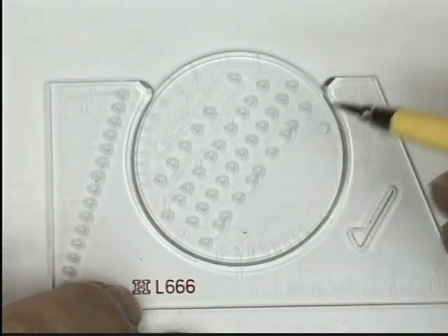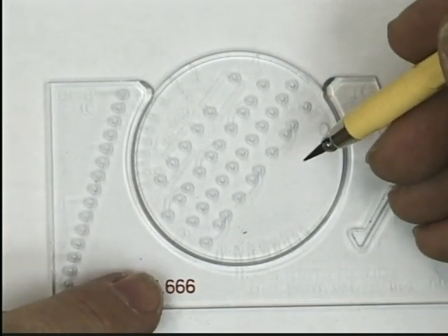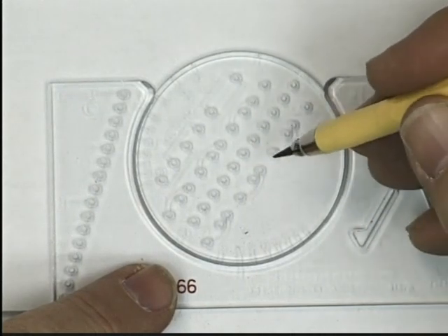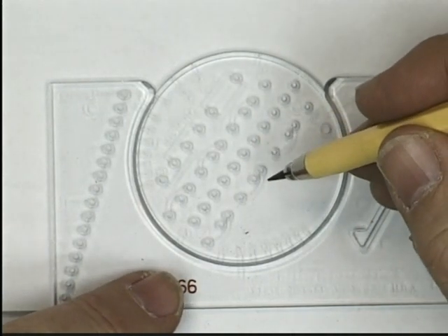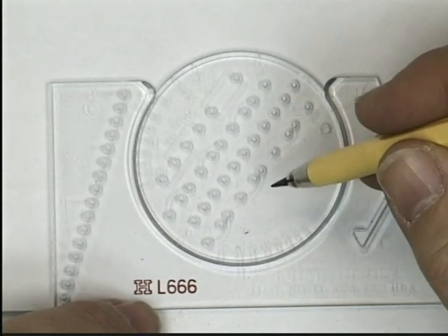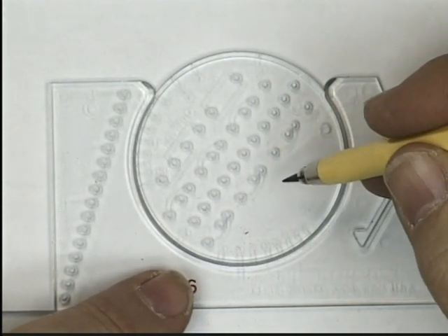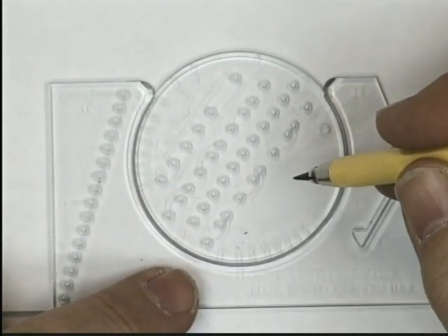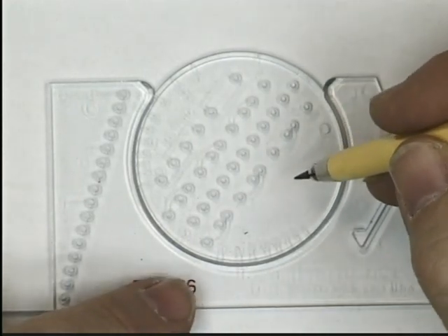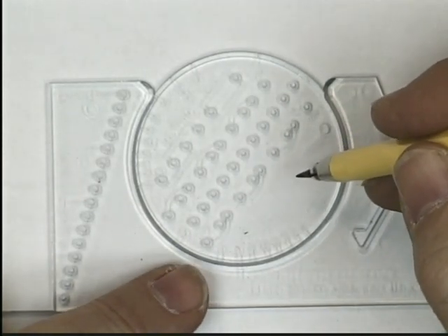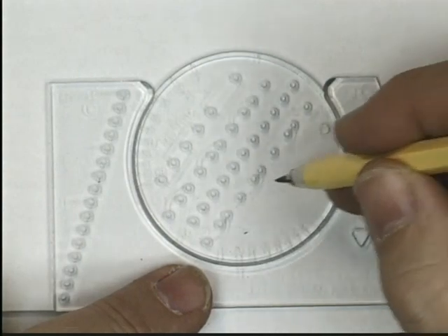Now, the way this is used, again, I use a conical point pencil, usually with a very hard lead, because these are going to only be guidelines. The thing about a guideline is it should be so light that you're the only person who can see it, and when you make a copy of your drawing, it will not copy. I'm going to make these a little darker than usual just for the video.